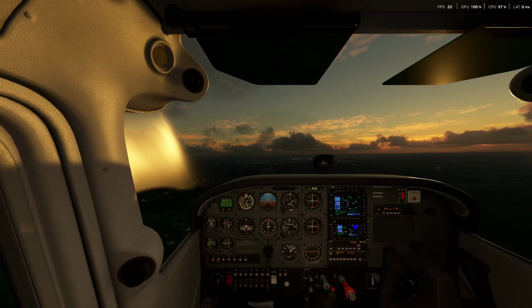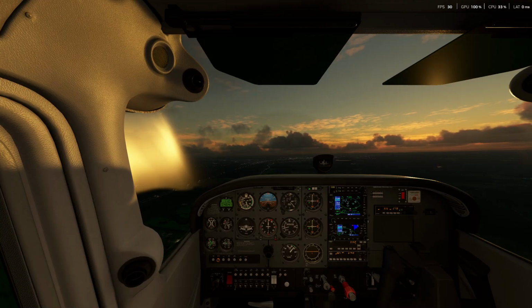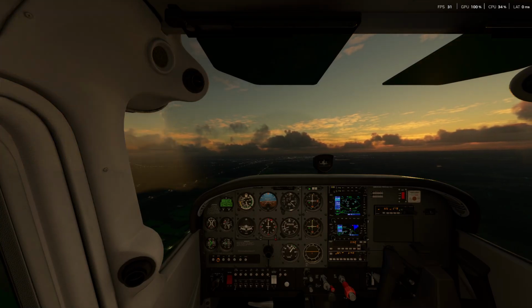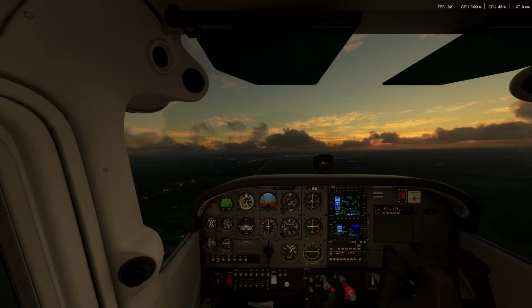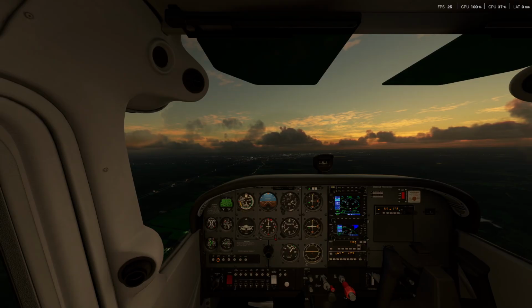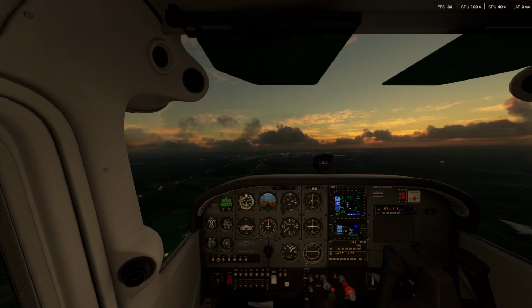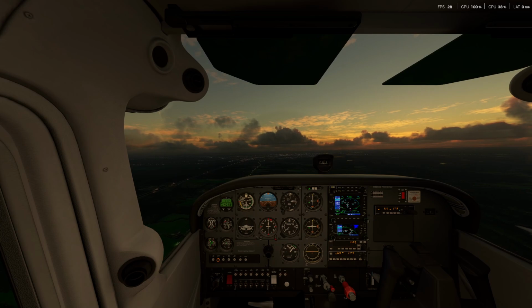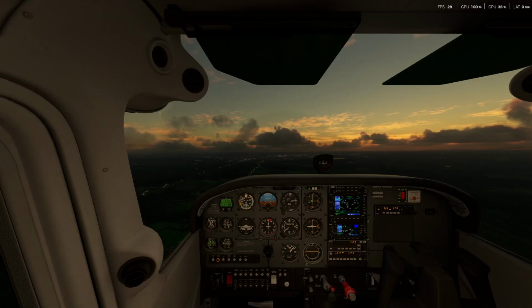At about 100 knots right now, so I'm going to descend at about 500 feet per minute. I'm going to adjust the RPM just slightly there, but not a whole lot. We let the airspeed go just because we have quite a bit now. So we're going to descend down to 1,800 feet. As we cross midfield over Moncton, we'll descend down to about 1,200 feet.